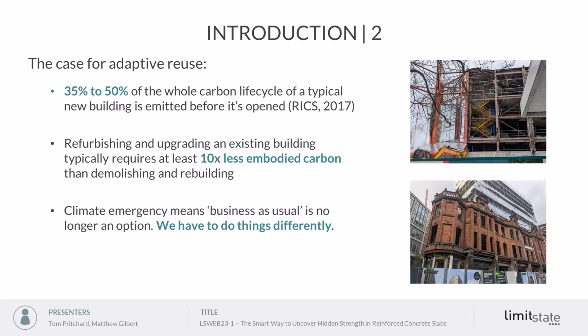On the other hand, if we refurbish and upgrade an existing building, then we're typically looking at around 10 times less embodied carbon than demolish and rebuild. So an order of magnitude reduction. And clearly, climate emergency means that we have to do things differently. Business as usual is no longer tenable.